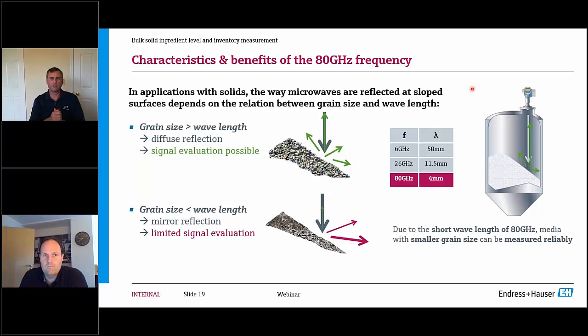So there will be no concern about the level keeping up with the rate of filling inside the silo. Again, you want to make sure that if you have your level sensor here, you fill over on this other side. You don't want to fill directly into the path.